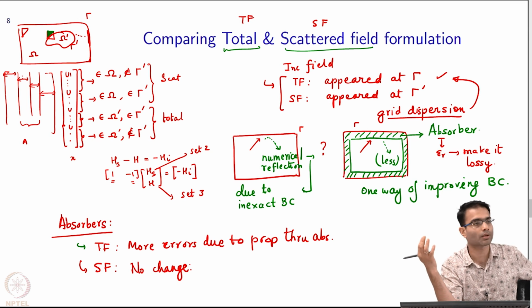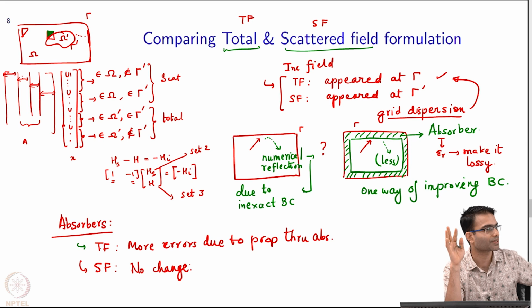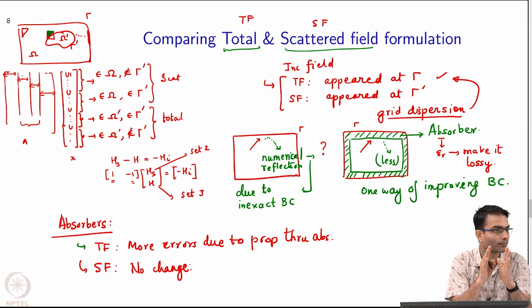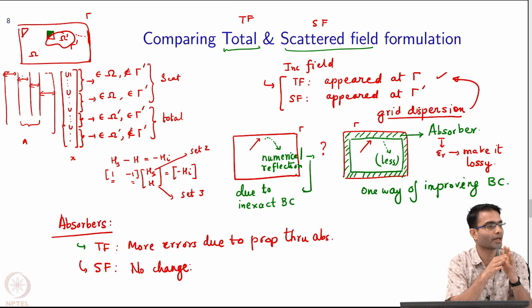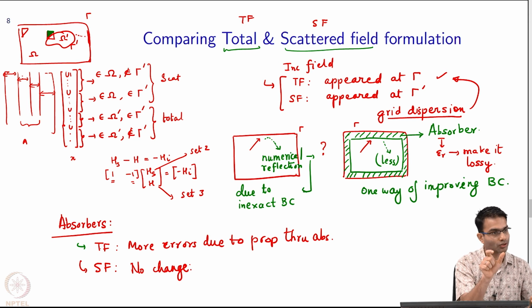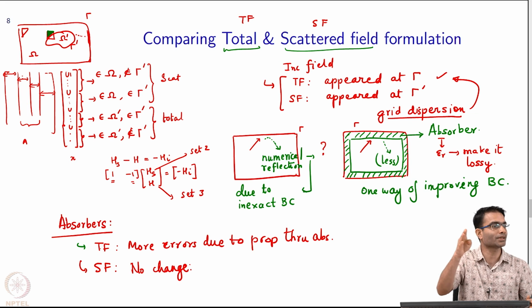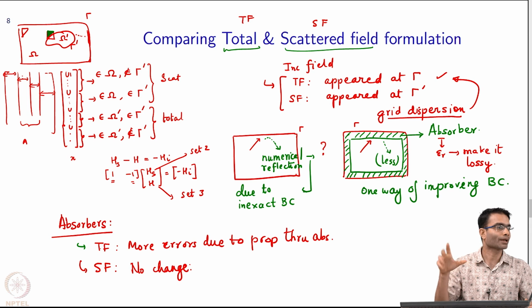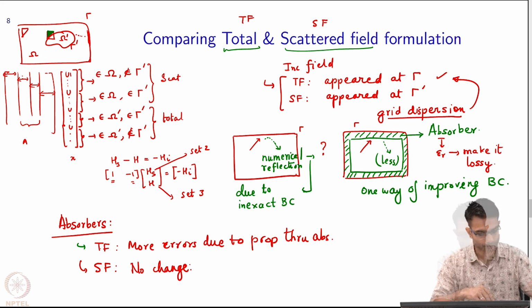And the design of these absorbers is another separate area of research altogether. You know that if you introduce a loss abruptly, what will happen? You will get a strong reflection. So, there is a lot of art in this: make the absorbing loss component gradually, adiabatically increase from the boundary. That makes the reflection very, very less. So, all of these things are tricks used in physics and electromagnetics to make high quality factor resonators and so on, but that is a separate topic, okay.